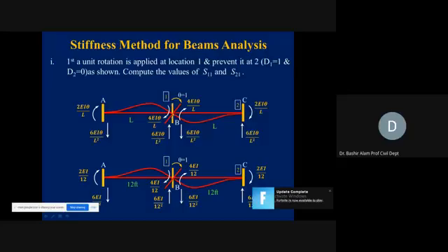Now, at a fixed support we cannot rotate. So what we do initially, we provide a hinge support here so that we allow this rotation. So if you want to show here, you can show a hinge also, but this kind of rotation is also okay. At the bottom sketch now, we apply our own condition now. Remember here, if you see, we don't show any actual loading because here we want to show just now the unit displacement corresponding to the D1.